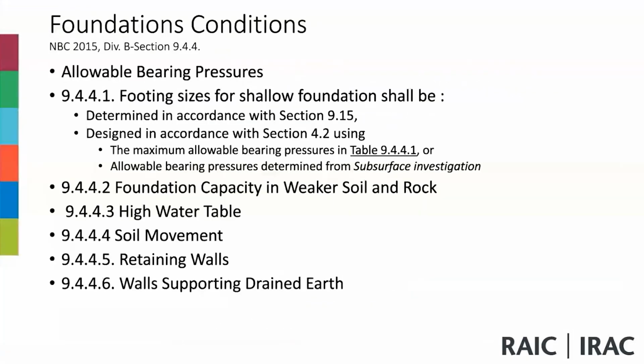Foundation conditions, 9.4.4. So allowable bearing pressures. We're looking at 9.4.4.1, footing sizes for shallow foundations shall be determined in section 9.15, designed in accordance with section 4.2. Again, it sends us to section 4.2 using the maximum allowable bearing pressure of 9.4.4.1.